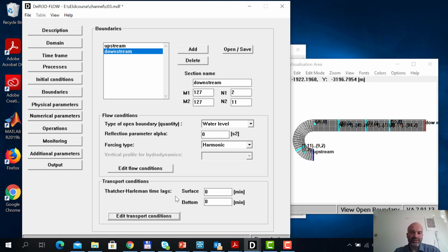Now, as soon as the tide turns from ebb flow, outgoing, to inflow, ingoing, the concentration will immediately change. So if you have an outflow condition of 0 salinity, then the moment water starts to flow in, it will have a salinity of 31 ppt.